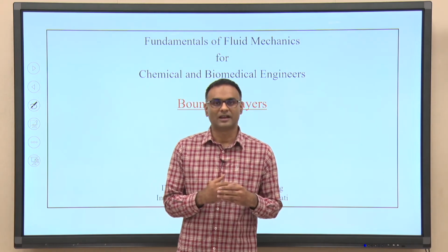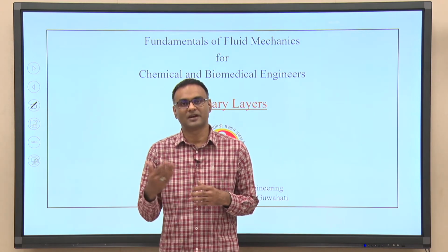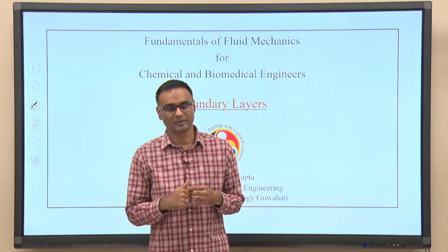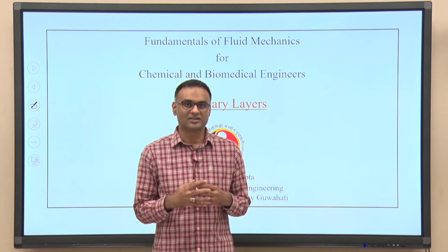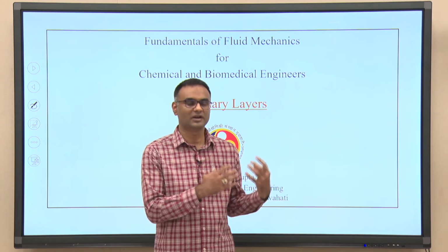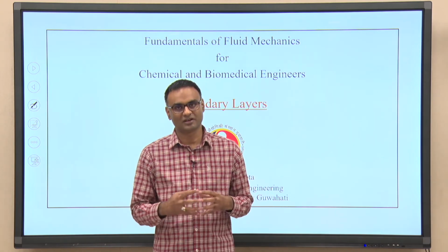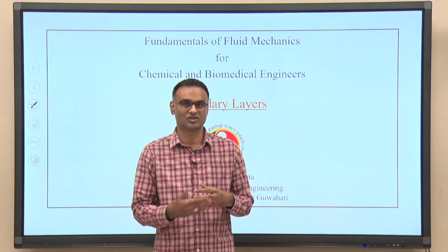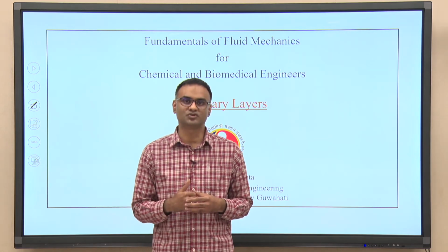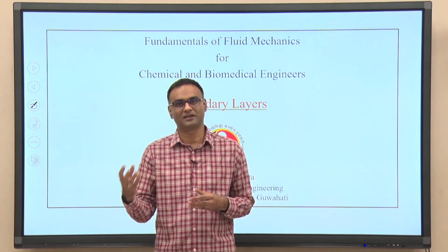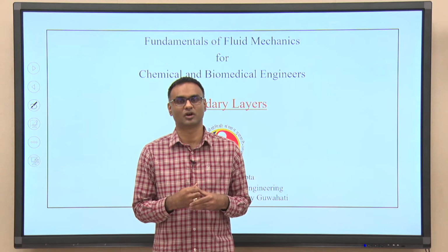So, there has been a lot of development using potential flow, finding out the solutions for different flow problems. However, there are some limitations for these inviscid flows, and they cannot, for example, satisfy the no slip boundary condition on the wall. They cannot predict the drag, etc. In today's lecture, we will look at boundary layer flows, and in this module, we will be looking at external flows in general. So, we will talk about boundary layers which, coupled with potential flow, can be used to analyze the flow over a plate, flow over spheres, or any kind of flow problems.